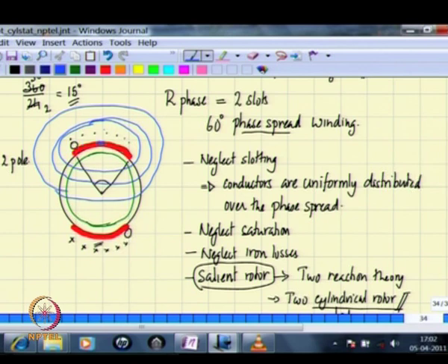It encloses all of these conductors, and hence the total current enclosed by any of these loops is the same, and therefore the MMF acting along this gap and that gap together would always add up to the total current here. And since these two air gaps are equal, we can say that the MMF is spent half here and half here, but then flux here is going in and there it is going out. So, the MMF acting would be reversed, and therefore all along this region the same MMF is acting, equal to half of the total MMF.